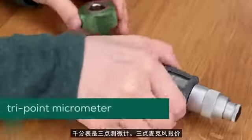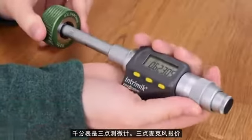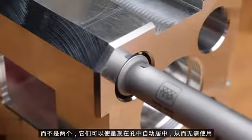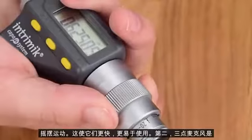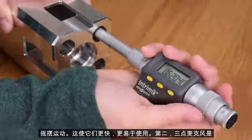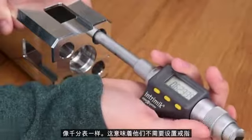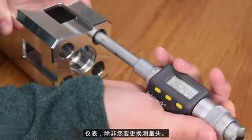A variation of the dial bore gauge is the tri-point micrometer. Tri-point mics offer two big improvements over dial bore gauges. First, there are 3 measuring surfaces instead of 2, which self-center the gauge in the bore, eliminating the need for the rocking motion. This makes them faster and easier to use. Second, tri-point mics are usually direct indicating, meaning that they display an actual diameter instead of just a variance like a dial bore gauge does. This means they don't need to be set with a ring gauge unless you're changing the measuring head.